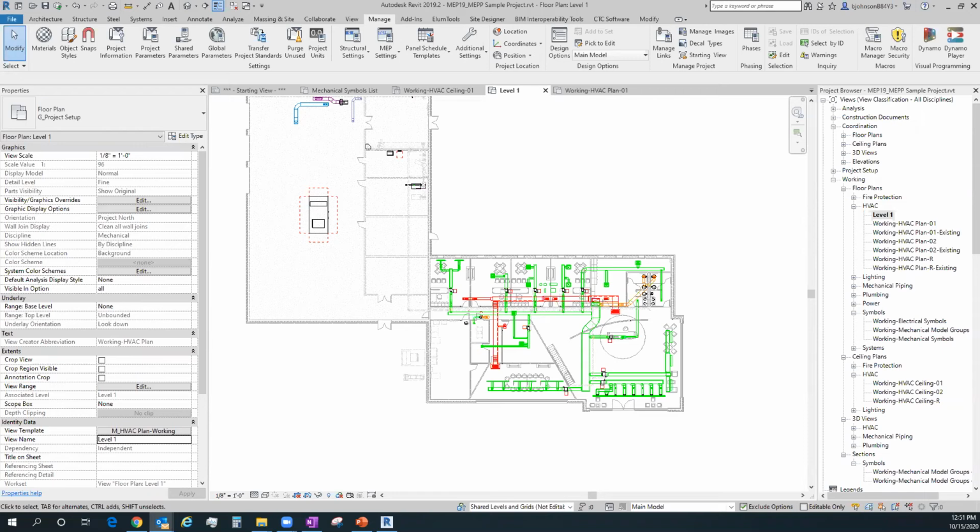Other things I typically do as far as how do I do a quick definition of something that happened. My fix is usually to define the problem first. And then as far as what are my tools in my toolbox, the journal files in Revit are one of my first places I would go because, as a BIM manager, I could go onto anybody's machine and suck the journal files off and open them up and read them. I could do that very quickly and usually know what the issue was before I even contact the user and say, hey, here's your problem.